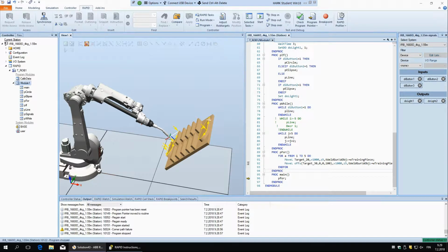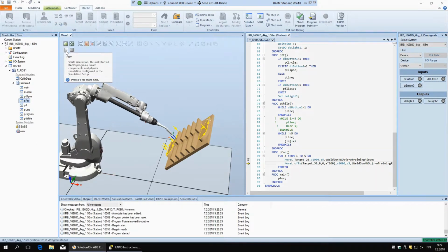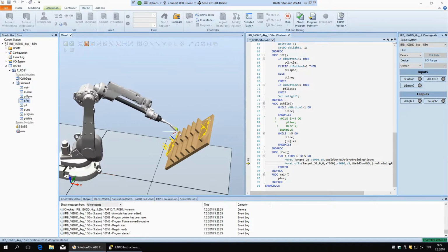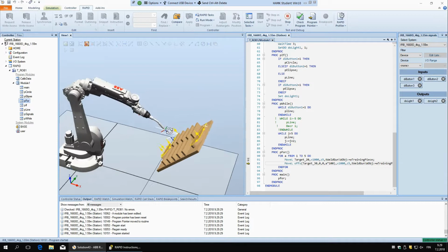But what we would like to do usually, if we are using it in the for loop, is not only move it to one point, but have it changing. So we can say a times 100. So it's going to take whatever value it is at the moment and change the offset like that. So if we run this now, it goes up, and every time it's going to be a different path.